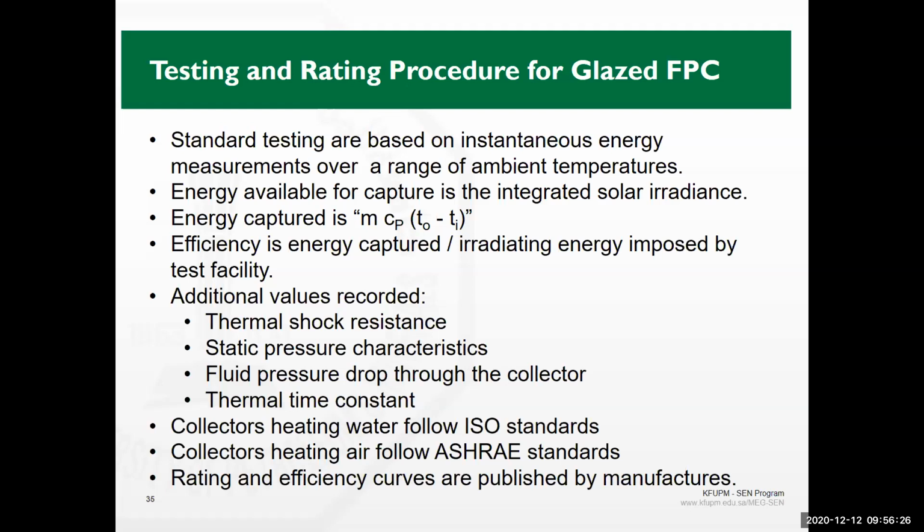It's not only the thermal performance that is going to be considered but also the shock resistance and the static pressure characteristics, which should be given. How much is the pressure difference across the collector, so that you can size the right pump that's going to pump the water through the collector.